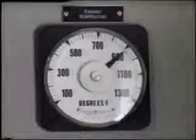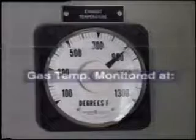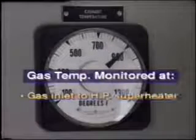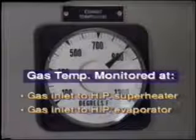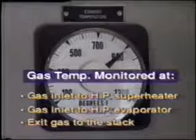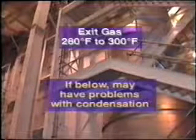The gas temperature is continuously monitored at various points throughout the HRSG, typically gas inlet to the HP superheater, gas inlet to the HP evaporator, exit gas to the stack. Generally, the exit gas temperature to the stack is in the range 280 to 300 degrees Fahrenheit, 140 to 150 degrees Celsius. If at any time the temperature falls below that level, we may run into problems with condensation from moisture contained in the gas.